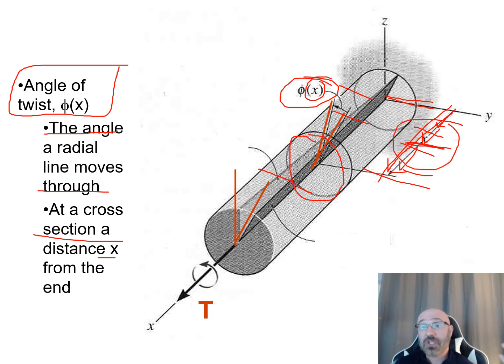If that's a question that we're asked, like how far away can you get with this applied torque before you start seeing a deformation over a certain amount, then that's important, how far out and what increments we're using. And we consider, can we do that? Or maybe we find roughly what it is by hand and then go in there and look at it a little bit more finely with FEA analysis using a program like SolidWorks.